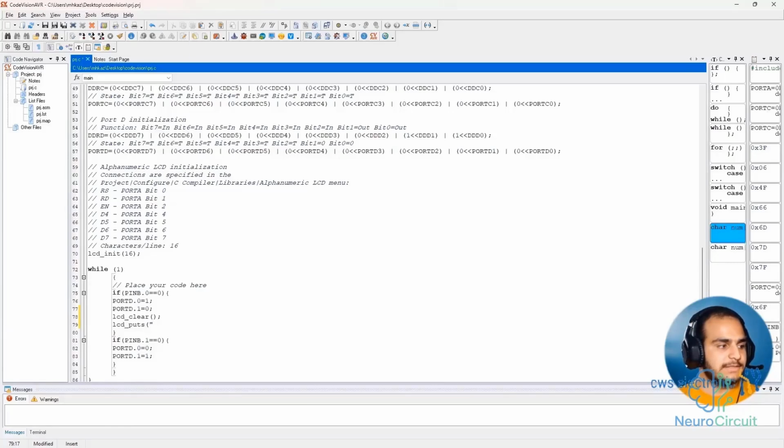For example, since this is our primary power on key, we definitely want to display the message "device air on". This message confirms the device's air system is operational. Now if we count the number of characters, it's 2, 4, 6, 8, 10, 12 characters. And for example, to center it on the LCD, I can add 2 spaces on each side. By itself it was 12 characters. With these 2 it becomes 14, and with these 2 it becomes 16. So this phrase will be exactly centered on the LCD.